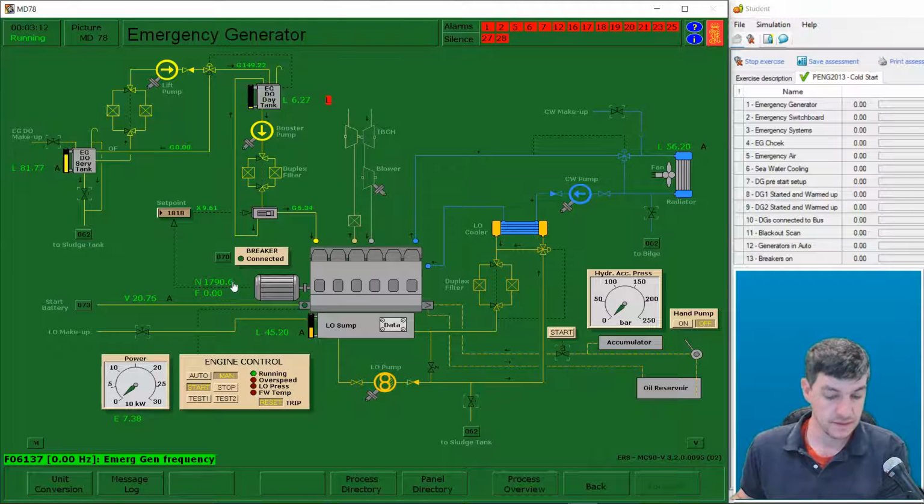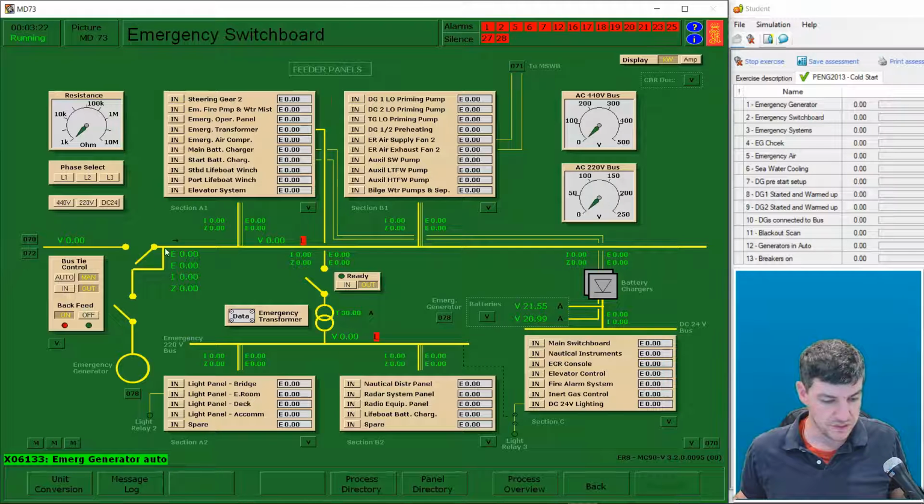so I think we are up and running. Ultimately, we'd like to turn this generator into auto. However, we're not able to do that just yet. There's a couple things we're missing. First is how the breakers get handled at the emergency generator. First thing we want to do is disable the ability for electricity to be backfed through the rest of the plant. And as well, we want to set the breaker control to auto so that it can automatically engage or disengage the breaker for the emergency generator to the electrical system.